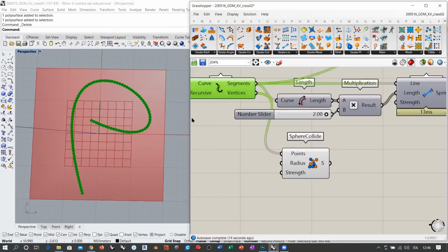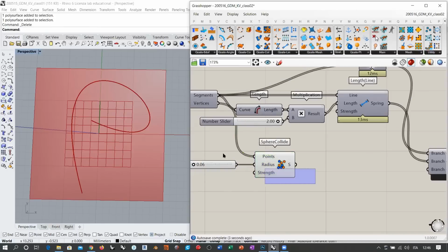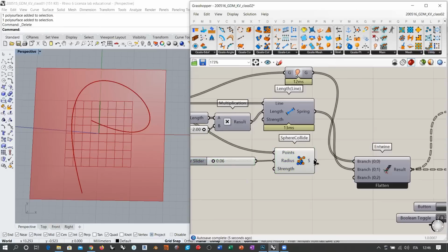And as the segments are very small, it means that they will basically receive an instantaneous push to bring all these vertices at 1 millimeter of distance between each other. So it's going to be very extreme, this goal. So I'm going to change this to 0.5 and eventually make it act progressively from 0 to another value. So this is going to be, for example, my collision.